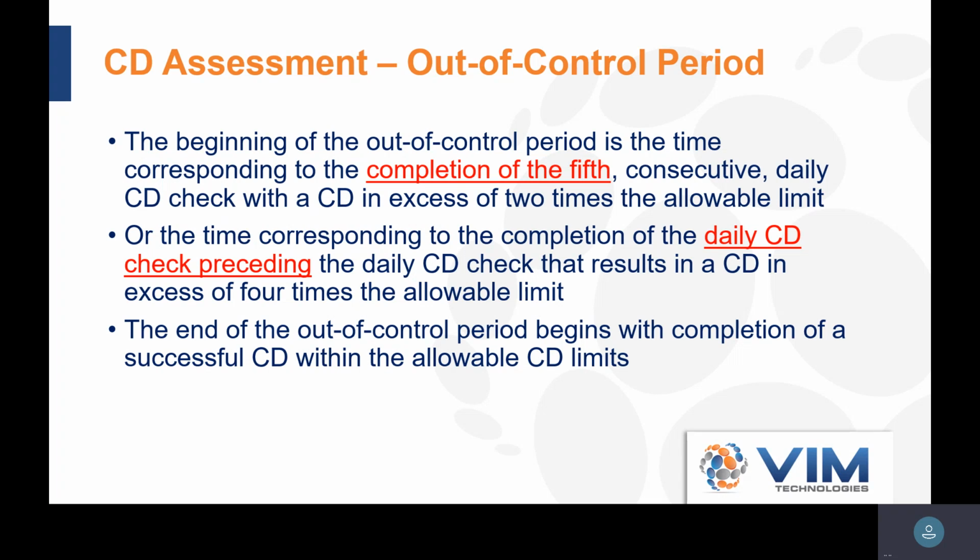Usually, like if it's a 4x out of control, usually there's going to be some performance issue involved. So it's not just going to be go out and hit the button and do another calibration drift check. Usually if you've exceeded that 10% threshold for NOx, there's something wrong. So there needs to be some diagnostics done to figure out what the problem is.